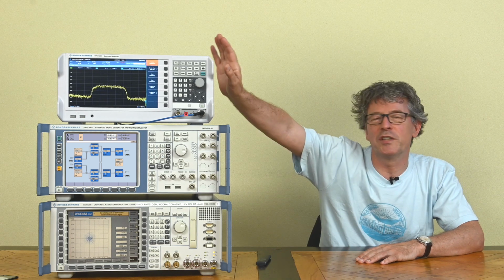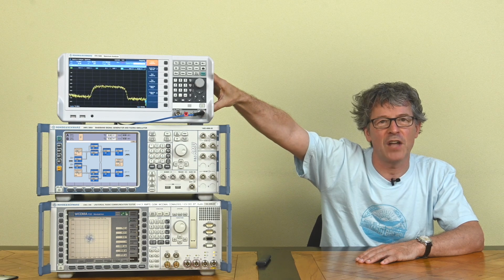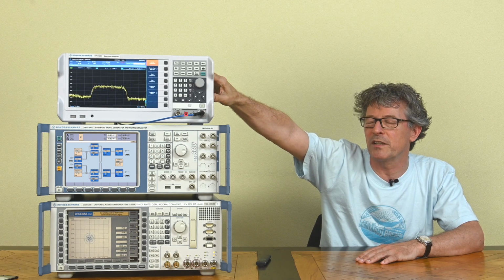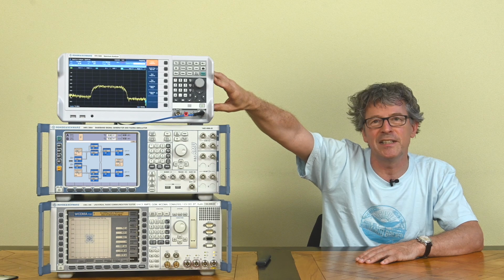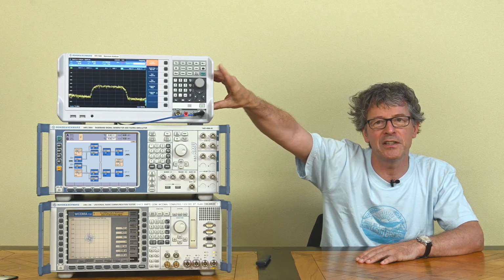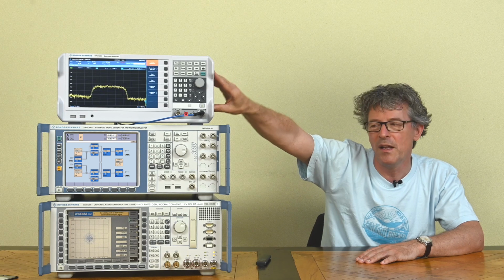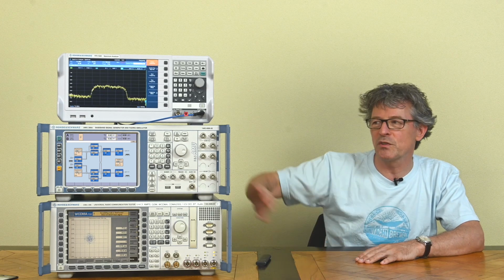For my experiments, I'm going to use the CMU for sure. I'm going to use the spectrum analyzer here so we can see some of the IF signals that are outputted by the CMU. I think you're actually seeing already here an IF signal when the unit is in wideband CDMA standard mode. So we see actually a carrier here on the IF output. And to test a little bit more on IQ signals, I will be using this fading simulator, because that's precisely how this fading simulator works. It goes into the IQ chain of the device, so that's kind of the perfect complement with the CMU for doing some experiments here today.